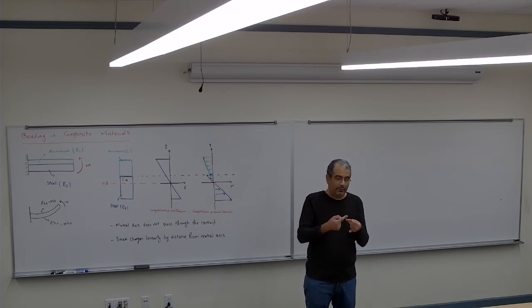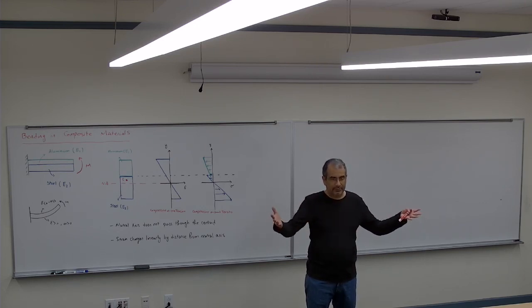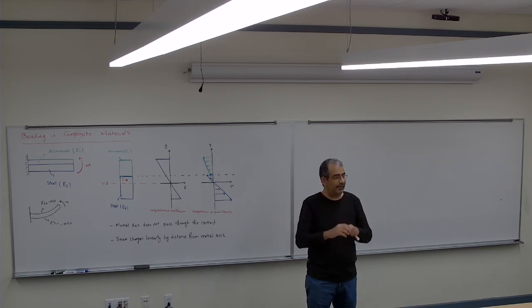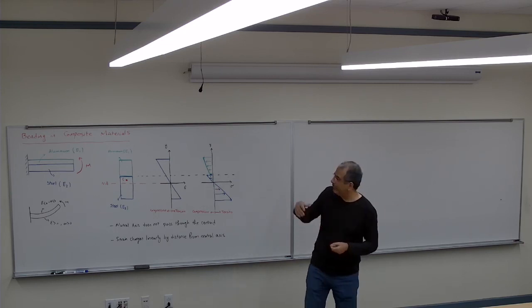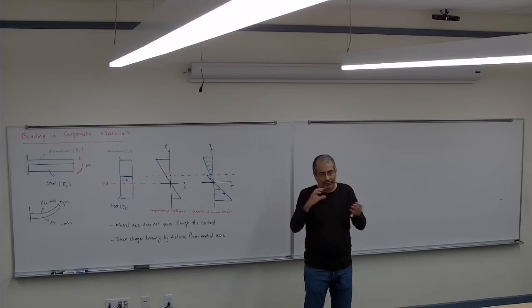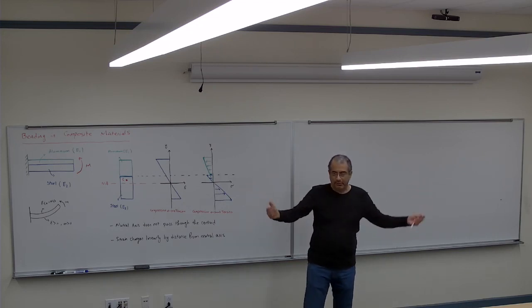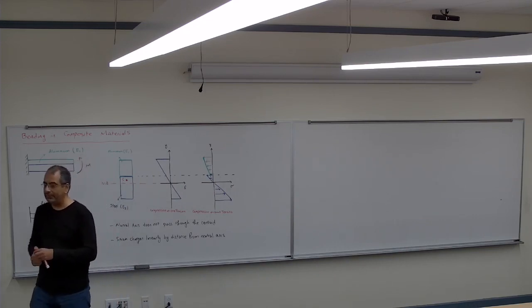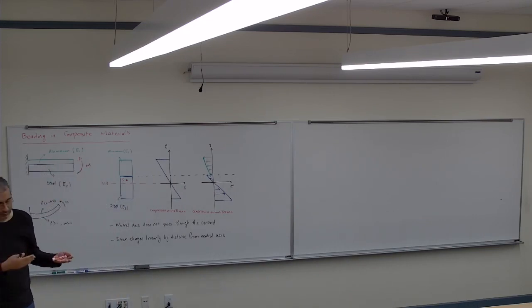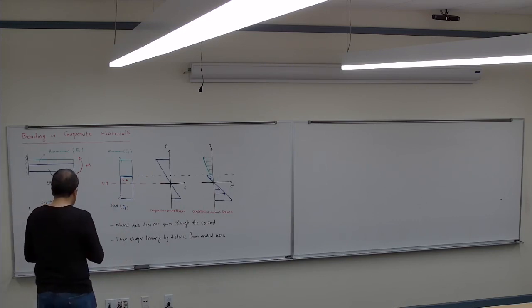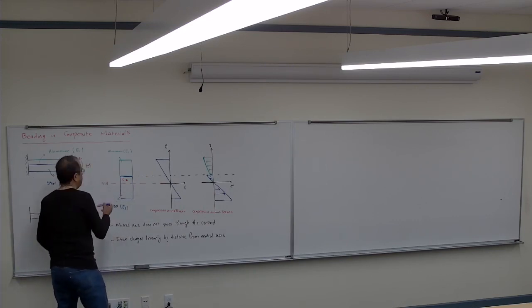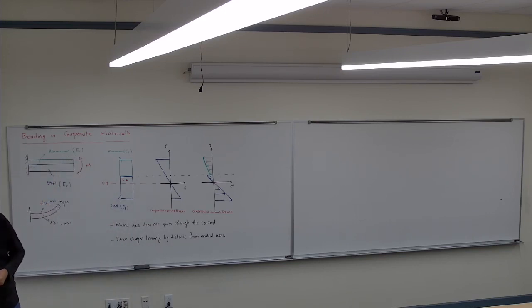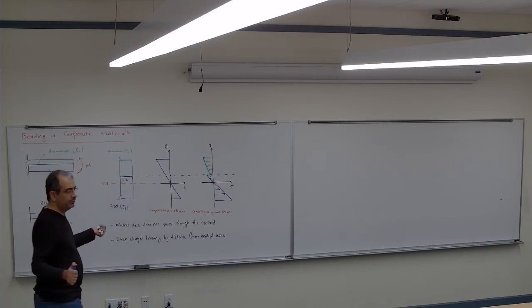The other way around, if I want to replace the steel with the aluminum, I should have much larger aluminum that can behave the same as the steel. So the section is not going to stay the same. Depending on which one I'm converting to the other, it's going to become smaller or larger compared to what we have. So the next step is to go ahead and replace one of them with another. In this case, I'm going to replace steel with aluminum.